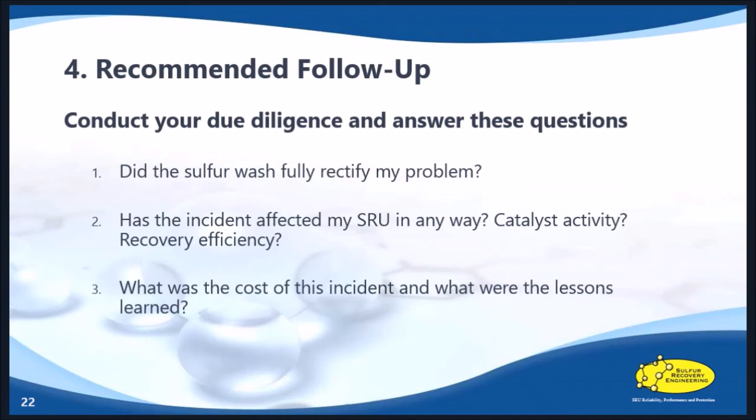We do sometimes do the sulfur wash, and like I said, maybe you might do the sulfur wash for something other than soot formation, but you need to really be sure that you identify the correct problem, and that the solution or the procedure that you followed rectified it. So much of what we experience talking to our clients is that when they get this soot formation, it's because they're starting up. They've already gone through what was supposed to be a 2-week shutdown, which turned into a 3-week, 4-week shutdown.